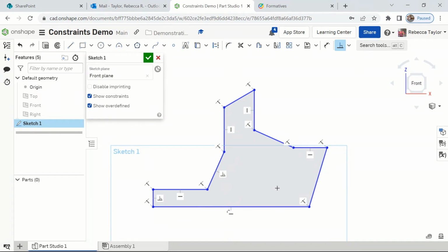So, automatic constraints. What you really want to see when you're doing this first part is the constraints that the CAD system will put on it automatically. It assumes that it knows what you want to do, but it doesn't do it without telling you, or at least most of the time it doesn't put these constraints on without telling you that the constraint is going to be there. So you just have to be really attentive to what you're doing. The CAD systems can be sneaky.